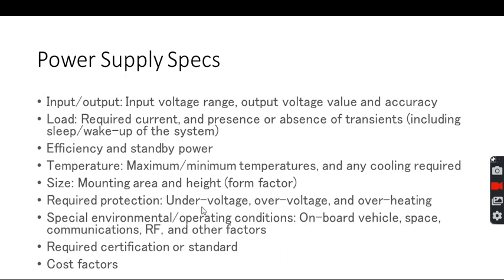So they'll have a fuse, or they will have relays in order to cut off if a higher voltage is coming in. If it is under voltage, it has to indicate that there is an under voltage input. In UPS you will find this. If there is under voltage, it will not charge, and it will show that it is under voltage. And if over voltage is there, it will trip. Like that. And if overheating is there, some of the systems, if highly heated, will automatically shut down.